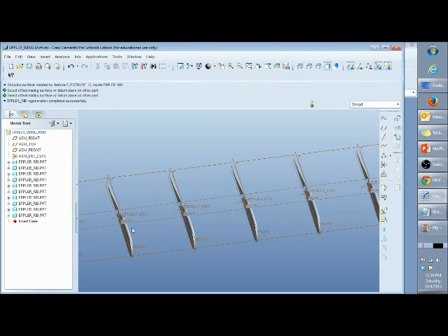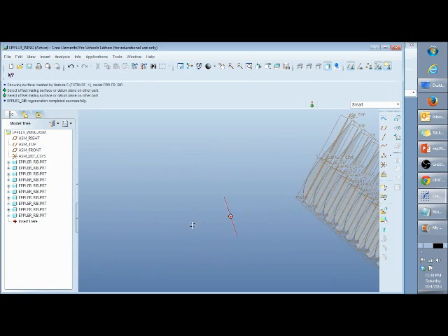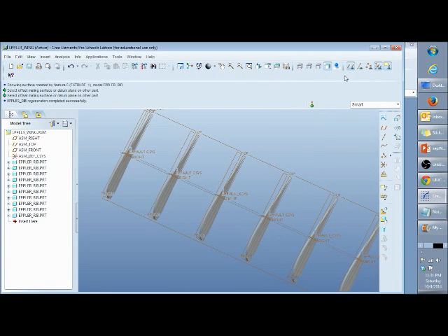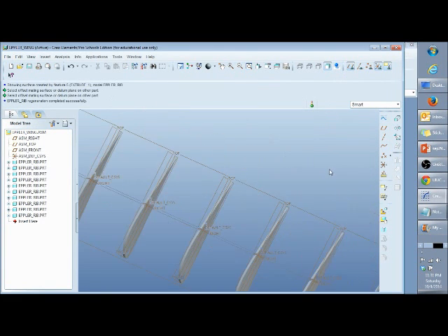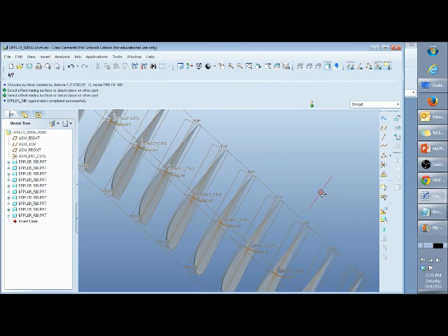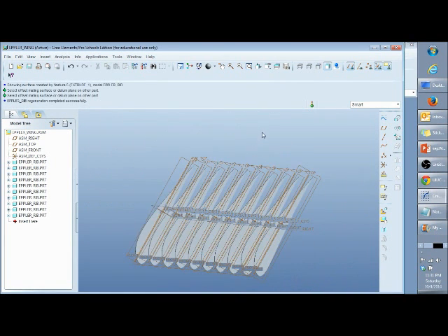So you want to find the spacing that should go between those through your own calculation. Modeling forums for model aircraft should give some pretty good recommendations too. That's where I got about the 3 inches or so. It's from one of those websites. So that step is done. So you have all the ribs laid out for your model.